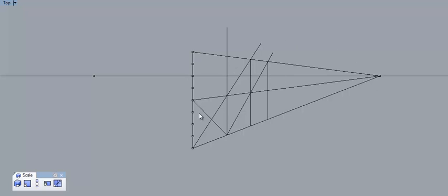And that tends to give you a better rotation visually as you guys are starting to draw this, okay? And I'm going to go ahead and just go through the same process that I went through with the first vanishing point. So I'm going to draw that 4-foot plane. And I'm going to draw that 8-foot plane, or the 4-foot on top of that. So we can see this is now starting to form as if we were going to be drawing a 2-point perspective of the exterior or corner of a building. We can start to do that.